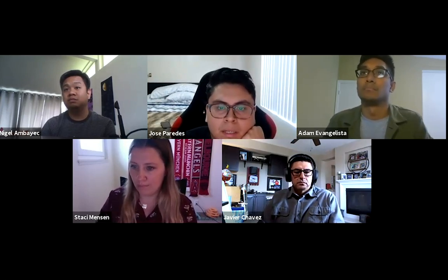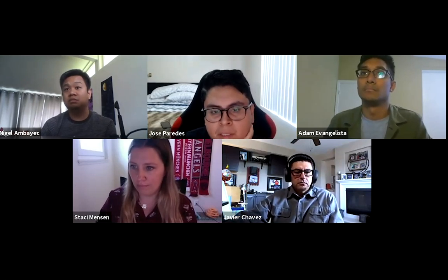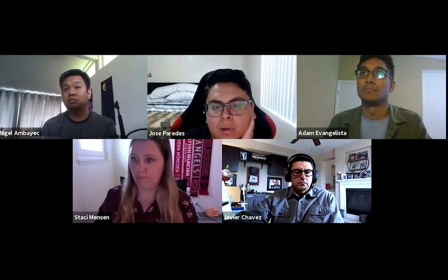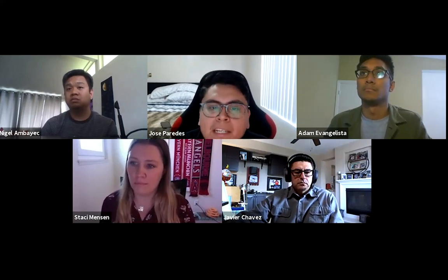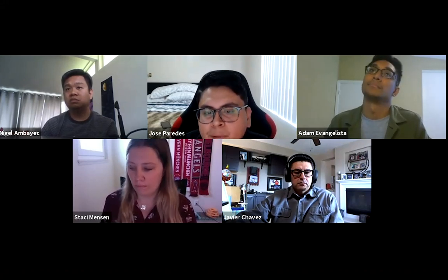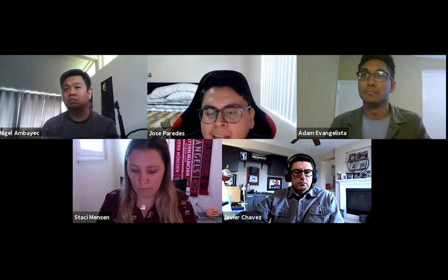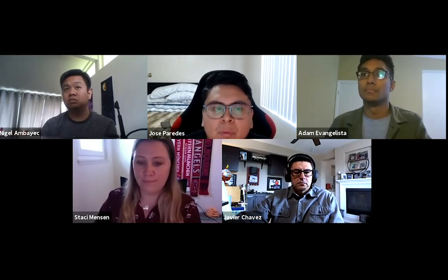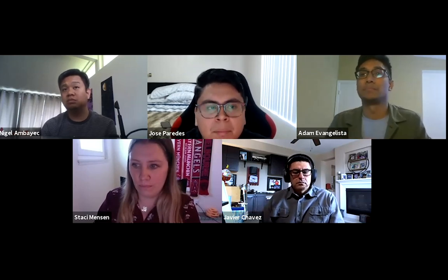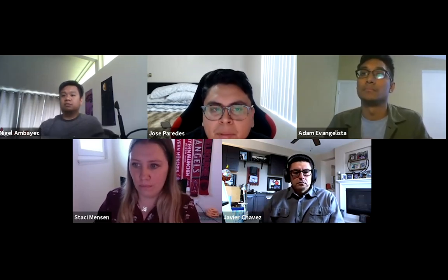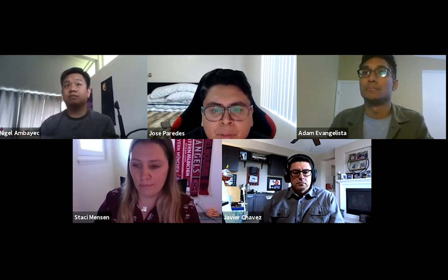I think one of these, this question from Claudio, as far as Task Scheduler, just to reiterate the point, can you use Task Scheduler to ensure that each member of a team automatically checks in a snapshot, for example, check in but keep checked out, of whatever they checked out each day? So yeah, it's what we talked about earlier with Javier. When you're doing the check-in option through Task Scheduler, you still have the option to maintain the files reserved to you, or checked out to you.